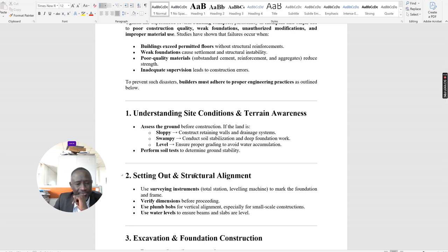When you excavate, you find different layers of soil, and then you reach maybe the brown type or whatever color it is, which is now uniform. So you can now say, okay, at this point maybe you go at least 2 feet or 3 feet, depending on the height of the building. But at least you know, as for the siting of the foundation, you are on firm ground. So that understanding of the layers in the excavation is very important. Sometimes even these senior people on site, those experienced workers, understand how to estimate practically that this is firm ground.